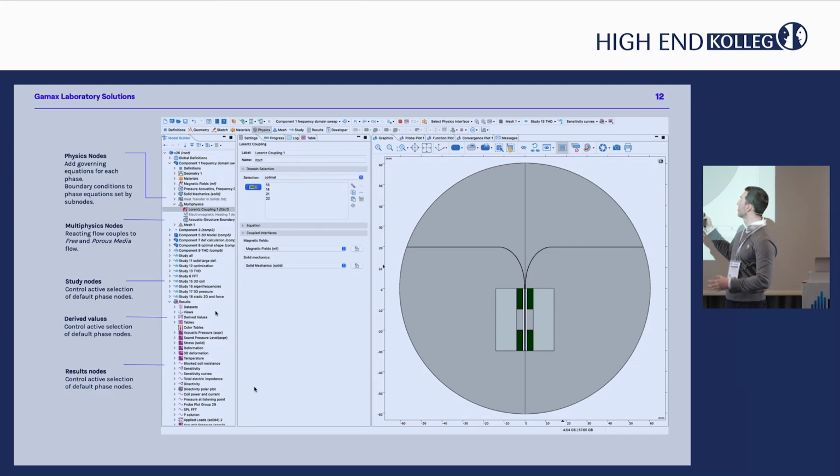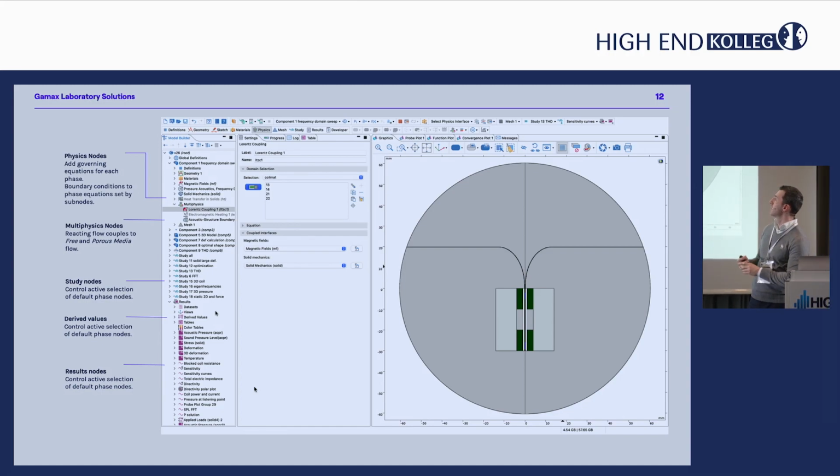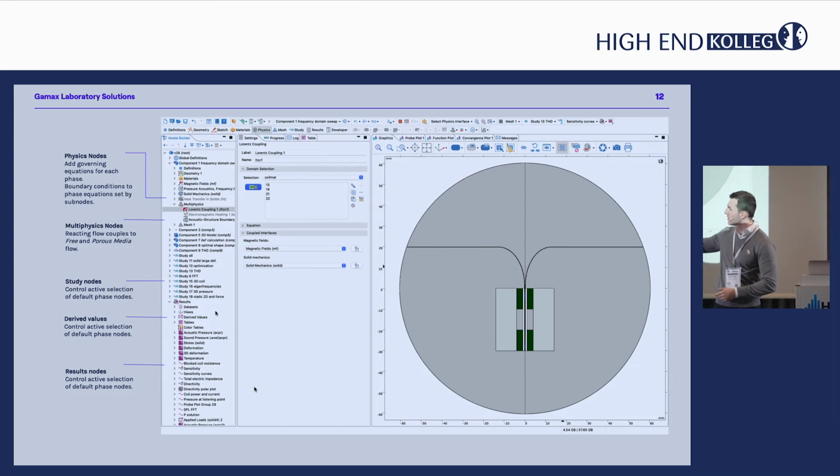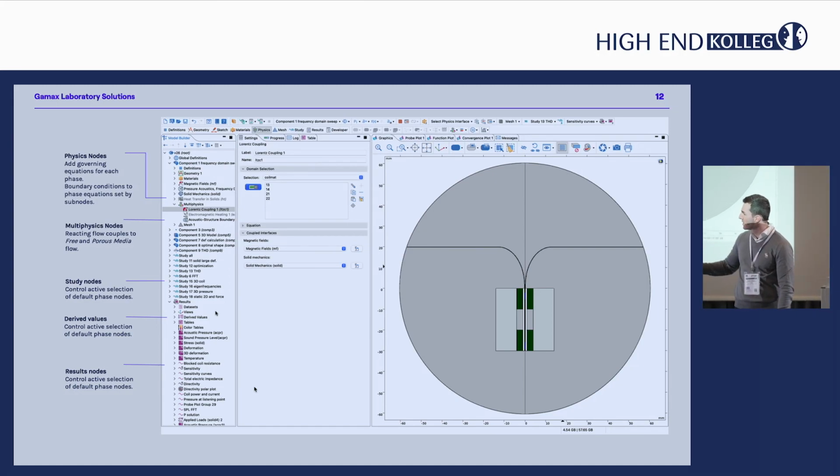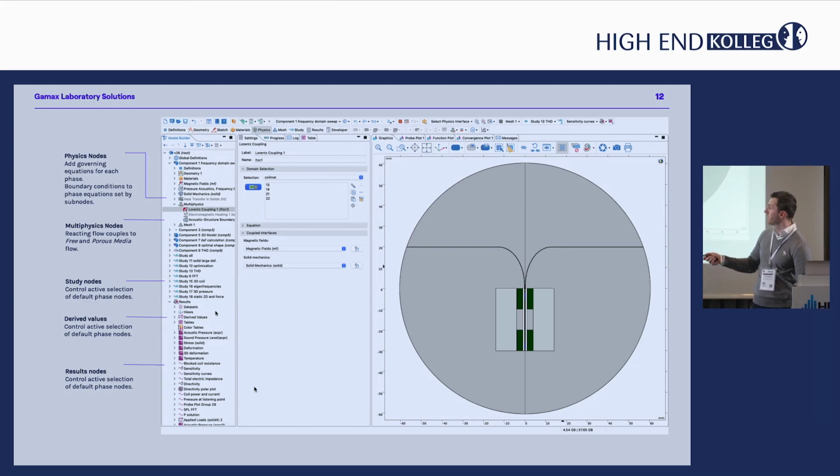That creates a movement of the solid parts, and with an acoustic-structure boundary condition, the motion is coupled to the acoustic field, so you can calculate the radiation pattern and the sensitivity. From the AC/DC calculations you can calculate all the relevant curves, like coil resistance, sensitivity and electric impedance curves.